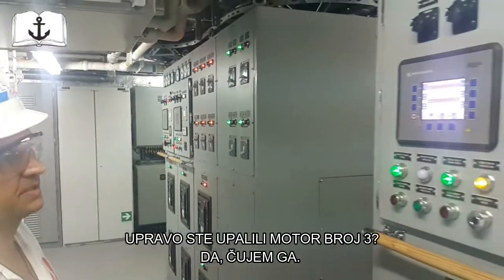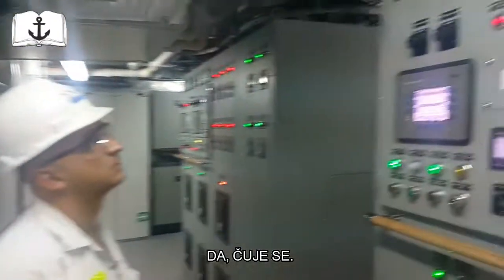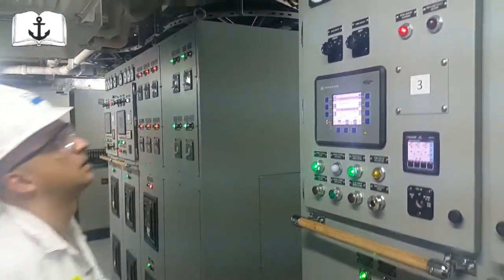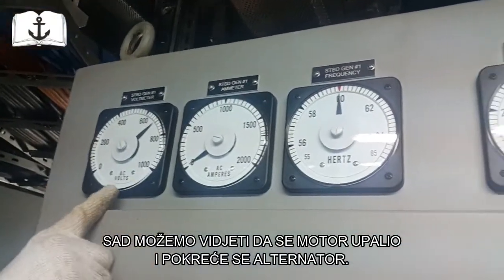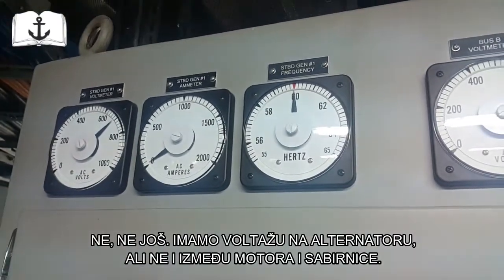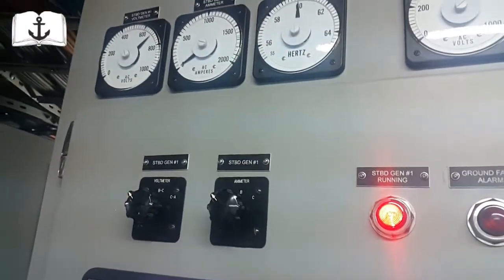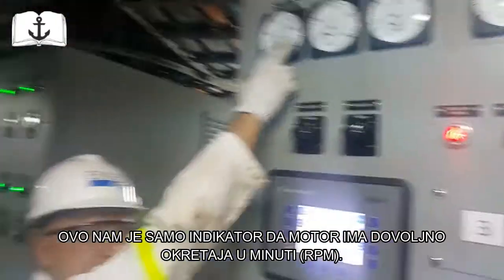Yes, the air is used. Now you can see the engine is running and also it's moving the alternator. That's why you have the indication. Now we have voltage? No, we don't have voltage. You have the initiation of the voltage on the alternator, but you don't have voltage between the engine and the busbar. It's the indication, let's say, that the engine has proper revs.